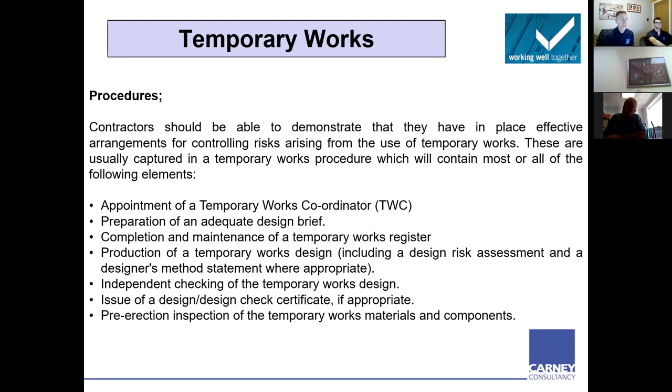Completion and maintenance of a temporary works register. Now, a temporary works register is a document which will be reviewed by the HSE if they come and have a look at your site. And again, a temporary works register is a log of all the temporary works you have. And this could be as simple as Harris fencing, the welfare provisions on your project, all the way up to design scaffold. And that will set specific criteria, such as the category that you've put it in, category 0, 1, 2, or 3, who's designed the drawings, who's undertaken the inspections, but we'll show you a template one on the next slide.